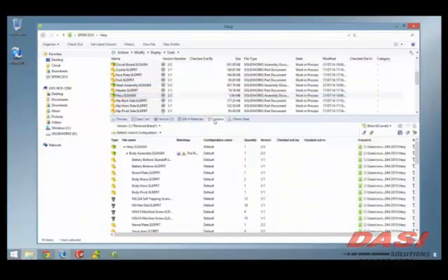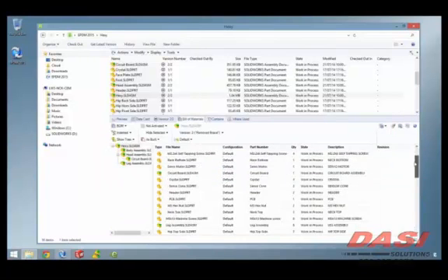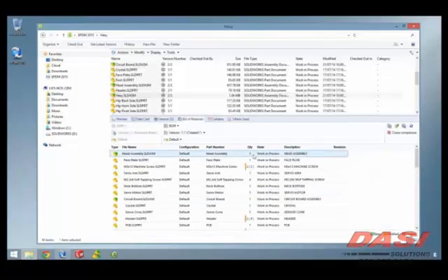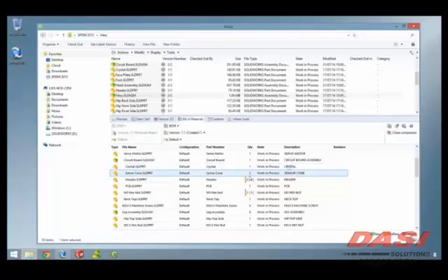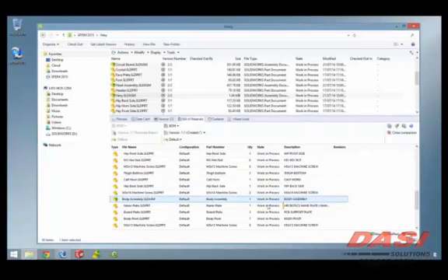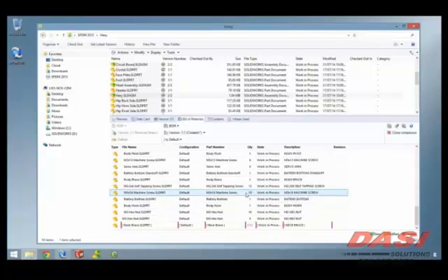We've changed the Windows Explorer interface a bit as well to make things more clear. You see that we get thumbnail previews for all parts and assemblies on the left-hand side, even in the Contains tab. And the Bill of Materials tab is much more tabular. There's some really simple column and row separations, and again, previews for each of the CAD files there. When we compare, we don't just highlight the entire row anymore. We can actually see that the individual properties or the thing that changed within each of these parts is actually flagged, not just the entire file arbitrarily.